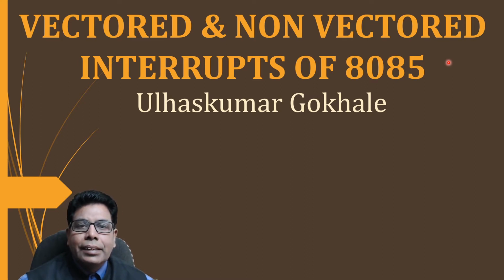Now interrupt is a facility provided by the microprocessor to communicate with the outside environment, and the microprocessor can divert its operation based on the priority. Now an interrupt is a process where an external device gets the attention of the microprocessor. When the microprocessor receives an interrupt signal, it suspends its currently executing program and jumps to an interrupt service routine or ISR to respond to the incoming interrupt.